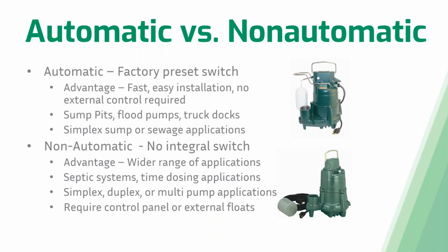This is great for septic systems where if you are putting a pump into a septic tank, you want to make sure that pump stays submerged at all times, since there are corrosive gases inside of that septic tank that will eat away at that pump. So keeping that pump submerged limits the opportunity for those gases to damage said pump.